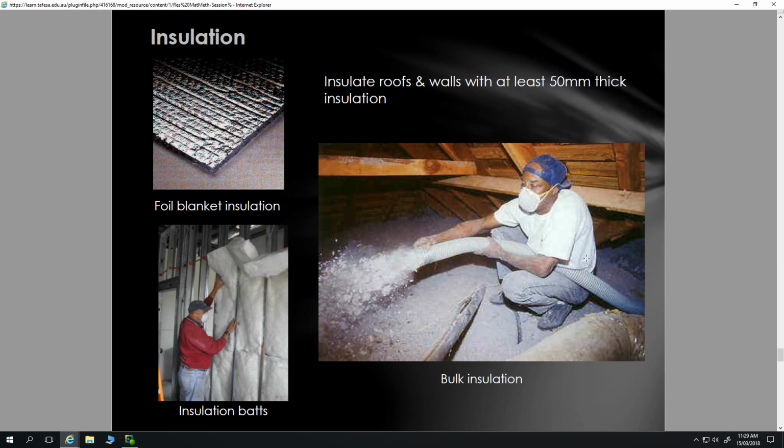So various forms of insulation. This one top left hand, that's like an air cell type insulation. There's quite a few products like that getting around now. That's a combination of a sarking and an insulation. So it's a building wrap, but it provides insulation. Typically they're only providing an R value of around 0.5, maybe 0.7. So it's only in addition.